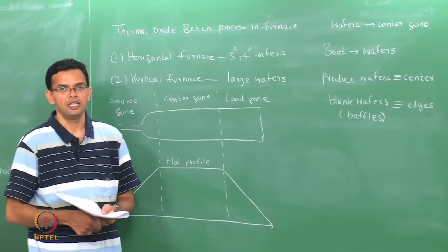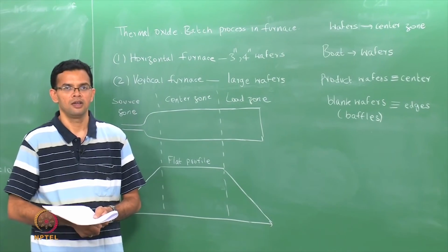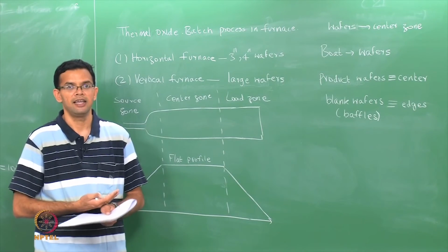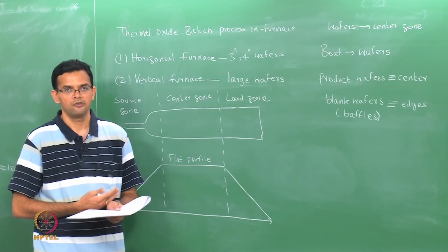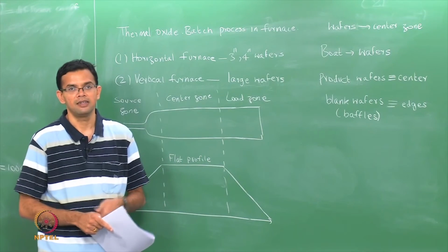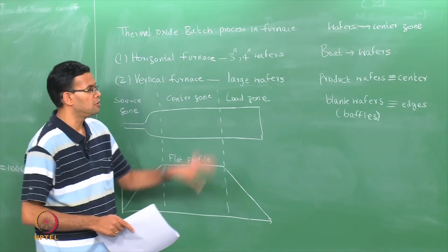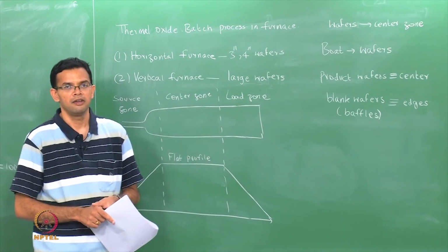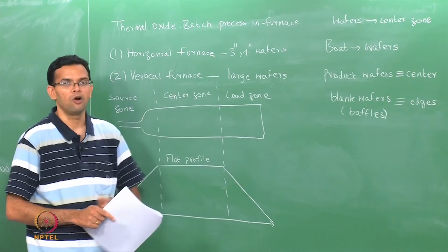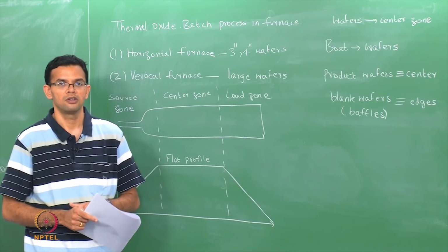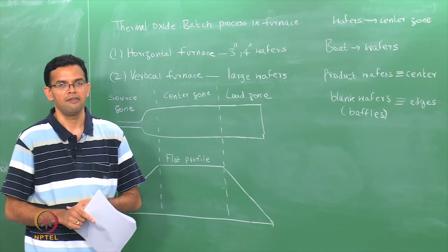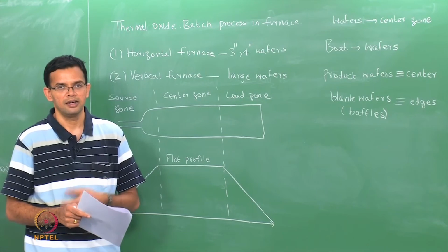We have only looked at the oxidation process so far. Another example of a grown layer is the nitridation layer or the nitride layer that forms on silicon. The process for forming the nitride layer is similar. We can also think of it as a grown layer where you have a nitride layer at the surface. So, we can think of similar models for diffusion and growth. You also have oxynitride layers where we have a layer with both oxygen and nitrogen in them.